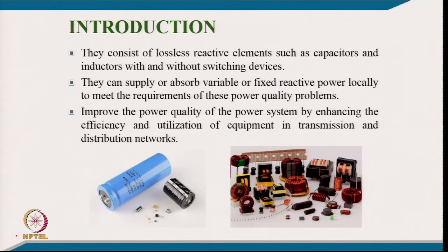This kind of compensation we are talking about is for when we have a sinusoidal supply voltage and a sinusoidal supply current, but certainly we might have a problem of reduced voltage, or a reactive power problem, or load unbalance in a 3 wire or 4 wire system, and even neutral current because of unbalanced load. So, in this linear environment we will be talking only about compensation by the lossless components, basically the inductor and capacitor.